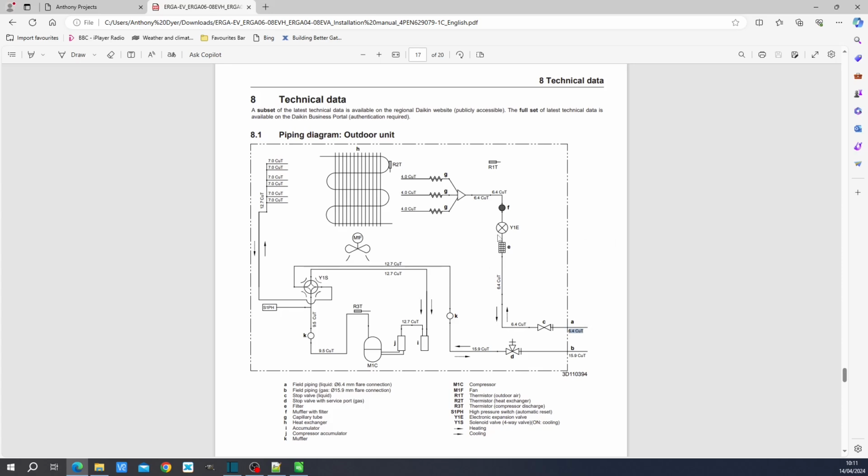And then we get to the expansion valve, and this is the valve that was oscillating between 12 and 16% very slowly, or it was oscillating very quickly depending on how stable pressures were. So this capillary tube splits in 3 into 4 millimeter capillary tubes, and each of these 4 millimeter capillary tubes is split again, and they become 7 millimeter capillary tubes.